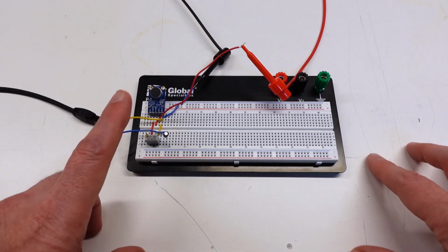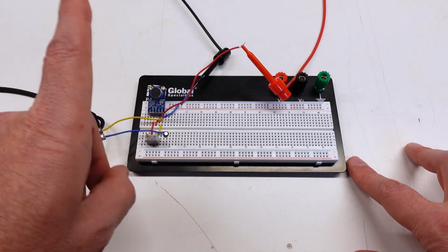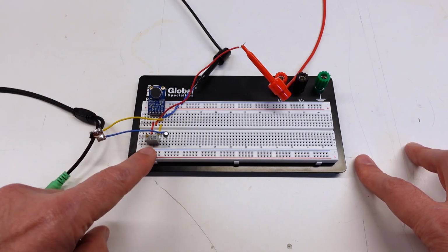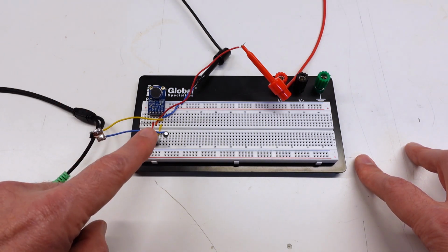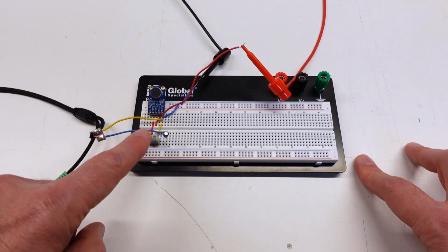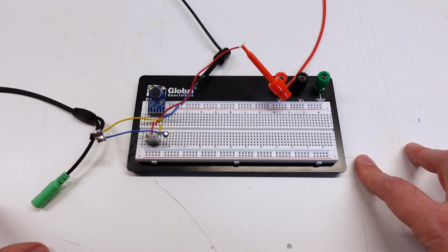So all I've done here is just put it on the breadboard. I've got DC power coming in through here. It's off screen to my 2718 power supply, 3.3 volts. On the output, I've got a 20K pot just to provide appropriate load for it, and also lets me dial it down quite a bit so I have an appropriate signal level going through this cable into my laptop for data acquisition and being able to hear what it sounds like.